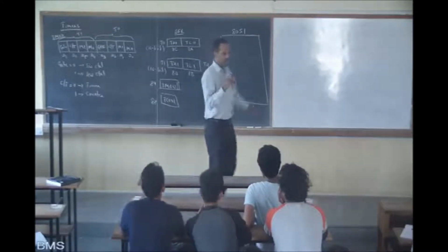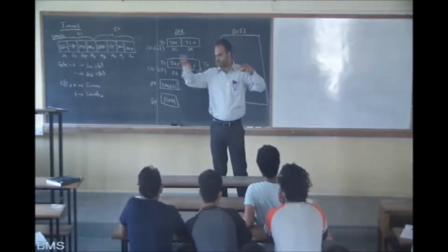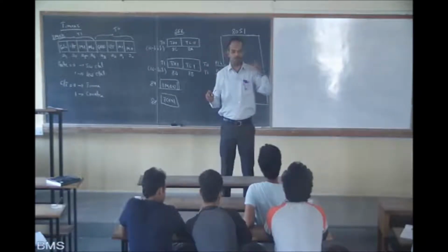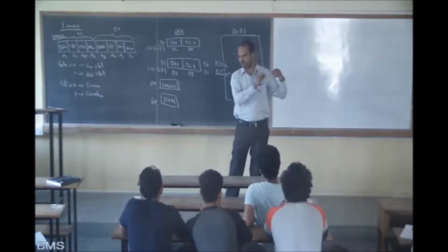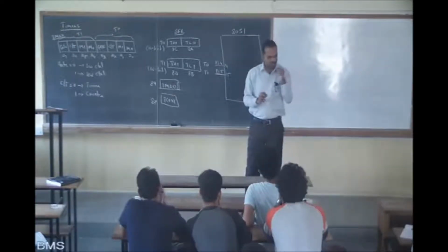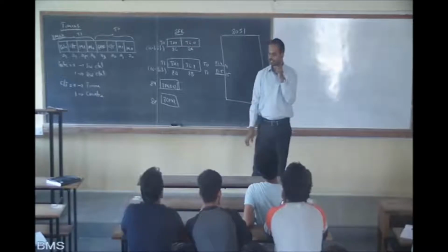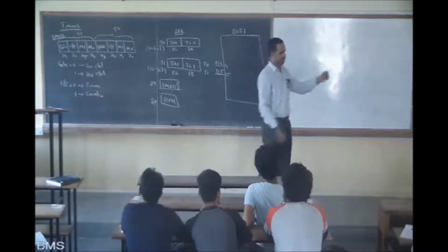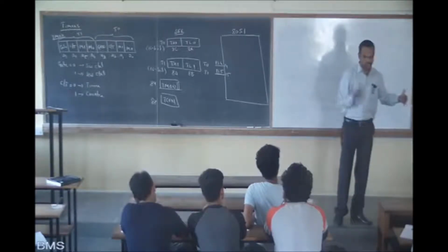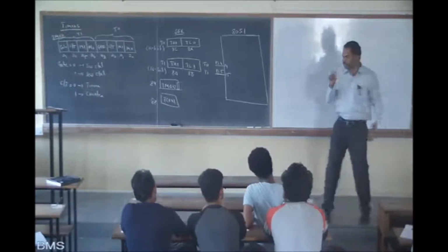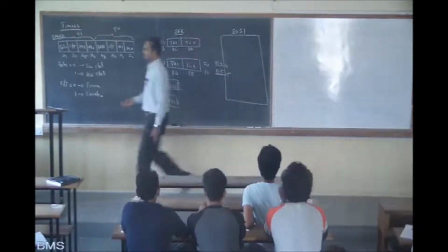When I say a timer, it is the same 8-bit registers, 8 flip-flops arranged in up counter manner. Given a clock pulse, you know what it counts, right? When I say counter, what does it count? How many clock pulses are coming inside, it counts that. These clock pulses will come from the crystal frequency of the 8051. When I say it as a counter, these are connected to this door sensor. Whenever somebody enters inside, a pulse is generated. That pulse is connected to P3.4.